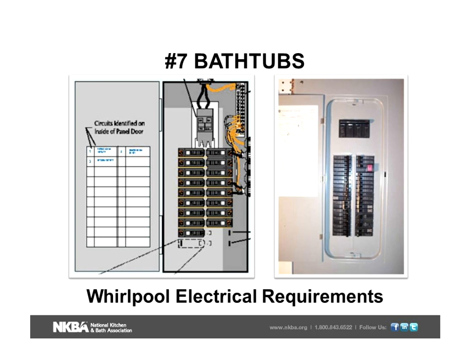On the left, we see an example. This is out of the Kitchen and Bath Systems PRL manual that NKBA has, and we can see that there are 3 slots available. Now, I could use one slot if I know that this whirlpool requires 120 volt. Most of the time, it would be a dedicated circuit. So going from this slot on the left to that whirlpool, direct shot, that would work for me. If it's 240 volt, I would need to add 2 of these slots together. So either way, with this panel, it could be added easily.